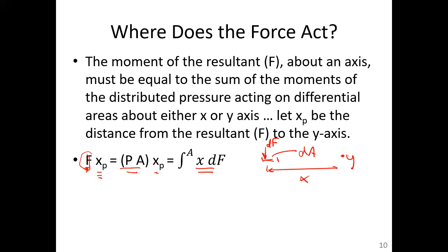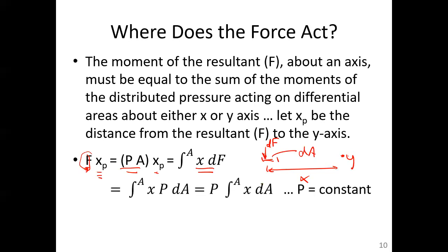And so what we're doing is we're slicing this area into strips parallel to the y-axis. There's strips of area dA, and each one has a different moment arm x to the y-axis. So we take the equation from above, and little dF is equal to P dA.